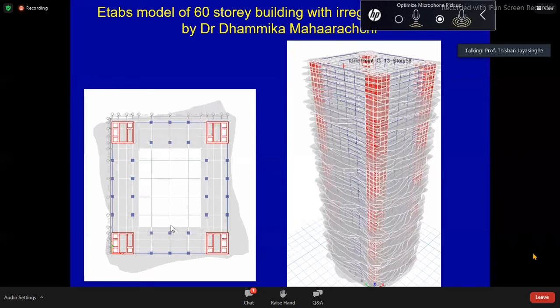And then again, you'll see, when you have such large diameter piles, it's not possible to maintain these basic rules like 3 times diameters. So generally, you have to go for something like 2 to 2.5 times diameters as the spacing between two massive piles. And so generally you will keep a distance of about 2 meters between two piles, because the diameter of the pile is 2 meters. So you'll see the basic rules that are followed by many engineers for small diameter piles are no longer applicable to large diameter piles.